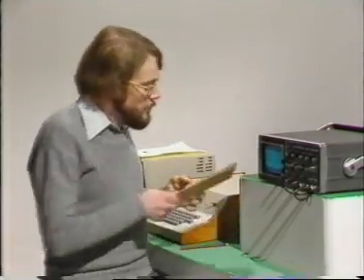Well, as far as amplification goes, the most promising system we've looked at is the resonant board. You've seen that it resonates at one particular frequency, and so it provides good amplification there. But the problem is that the amplification drops off as the frequency increases. But as well as the flexing mode of vibration of the board, this one, there are all kinds of other ways that the board can vibrate. And if we drive it at higher frequencies, we can excite these different vibrations.